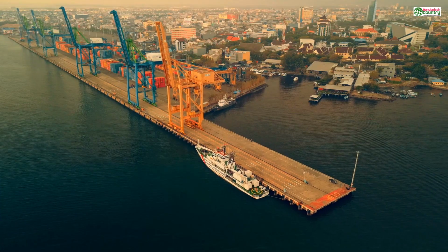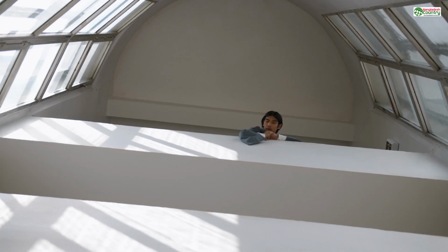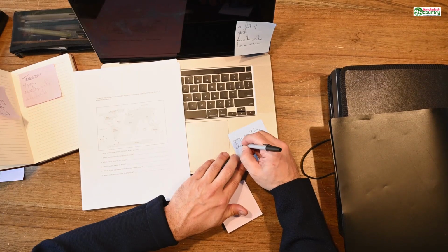You simply import your model, your STL or OBJ file, and you click a single button, usually called something like Inspector or Analyze. The software then does a full diagnostic scan of your entire model's geometry. It's not looking at how pretty it is. It's looking at the mathematical integrity of the surface. And then, like magic, it highlights all the problems. It will put bright blue or red markers on every single non-manifold edge. It will show you exactly where the holes are. It will point out any surfaces that are fighting with each other. Takes all the guesswork out of the equation.